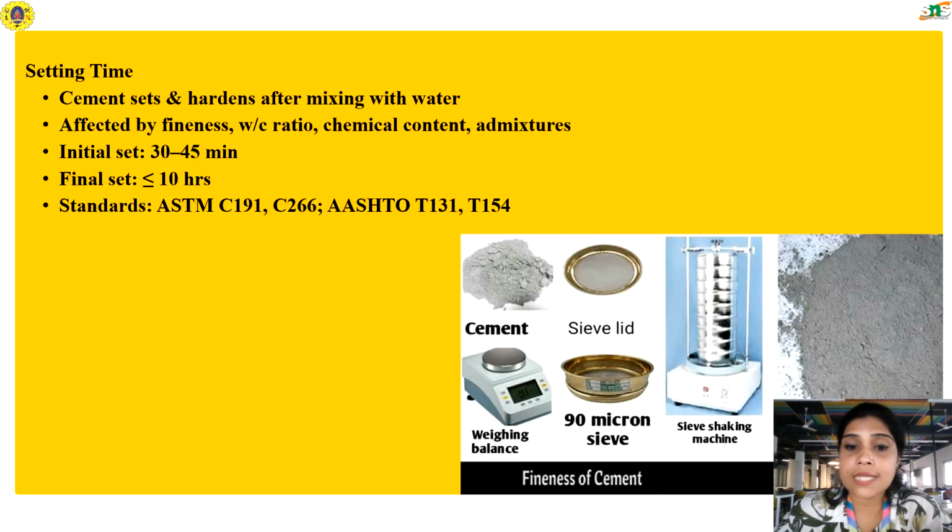Then comes the setting time. Cement sets and hardens after mixing with water. It's a universal thing. When cement is mixed with water, it doesn't immediately harden. Instead it goes through a gradual process called setting. Setting time is very crucial because it defines the window of workability of the concrete: the time during which mixing, transporting, placing and finishing must be completed.